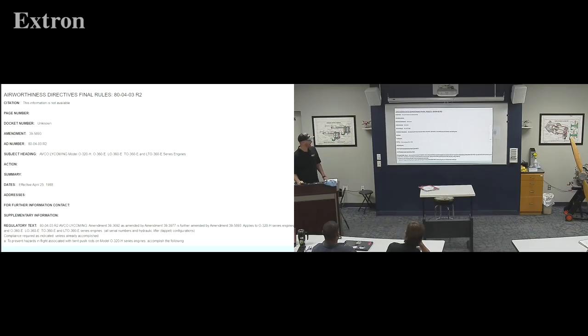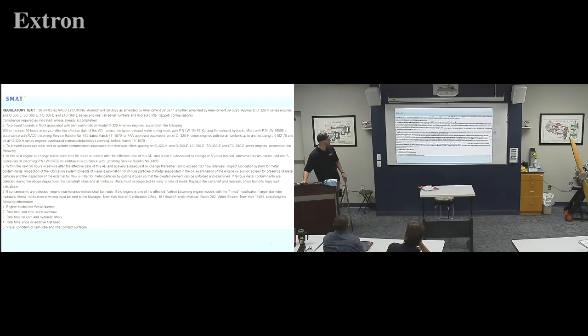One's talking about adding the agent, the oil additive, to all these engines. So on some of them, they are actual ADs. And basically, at the next engine oil change, but no more than 50 hours later, it's talking about adding the Lycoming additive to it.